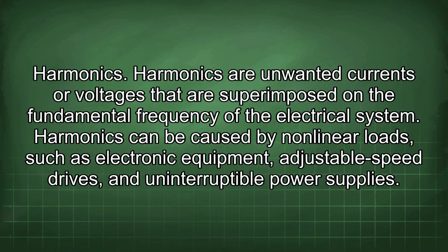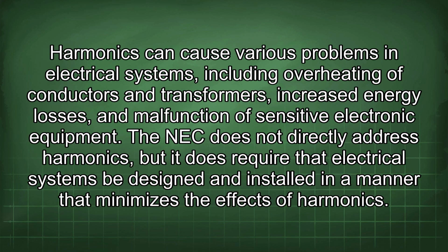Harmonics. Harmonics are unwanted currents or voltages that are superimposed on the fundamental frequency of the electrical system. Harmonics can be caused by nonlinear loads, such as electronic equipment, adjustable speed drives, and uninterruptible power supplies. Harmonics can cause various problems in electrical systems, including overheating of conductors and transformers, increased energy losses, and malfunction of